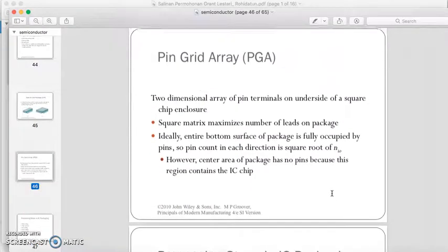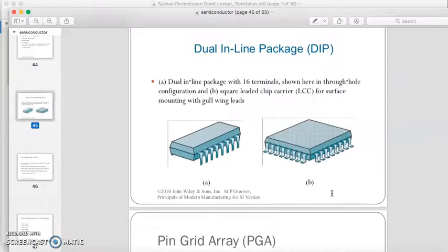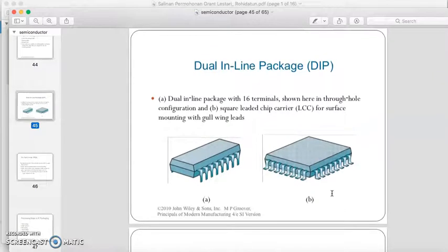this is the last stage in integrated circuit production. It includes the process of metallization to connect the electrical components inside the chip, and also assembling the lead to connect the circuit with the external unit, and also the packaging material to encapsulate the circuit or IC and protect the IC from the outside environment.